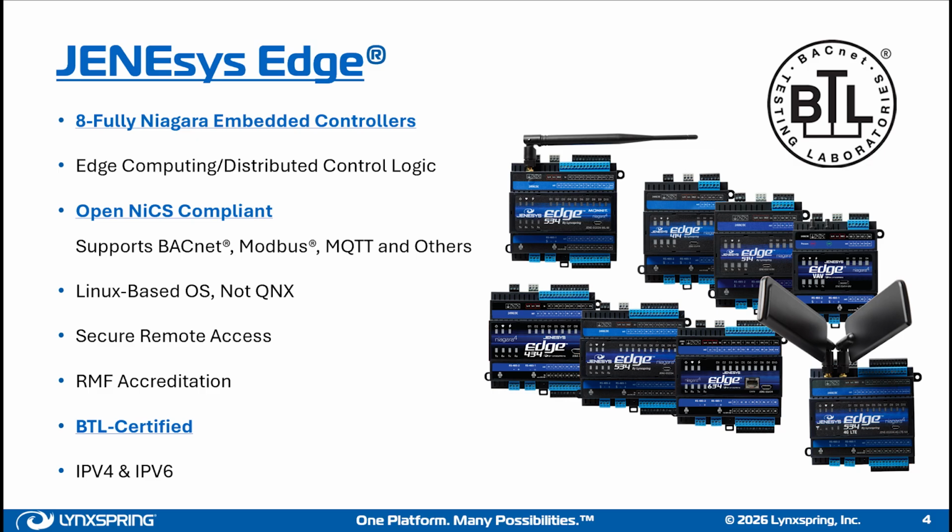Something that should be obvious, but is stated, we support all the open protocols, including backend Modbus. We include some sophisticated IP or IT type protocols like MQTT and others as well. We are Linux based, not QNX based. The previous JENEsys, as you may know, were QNX based. These products, including the JENEsys 9000, are now a Linux based product line, which inherently provides some degree of security along the way as well.